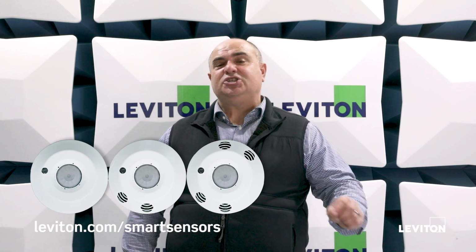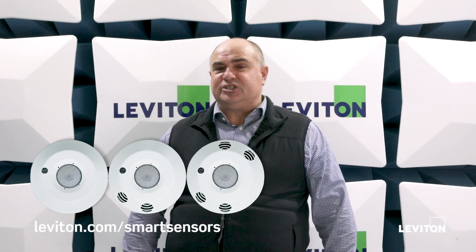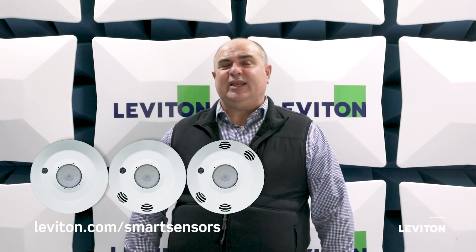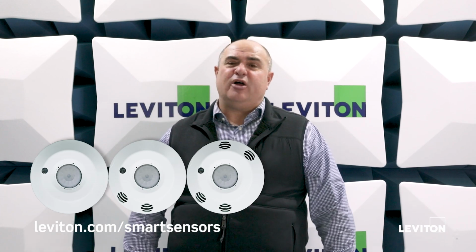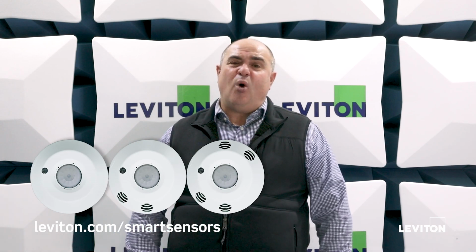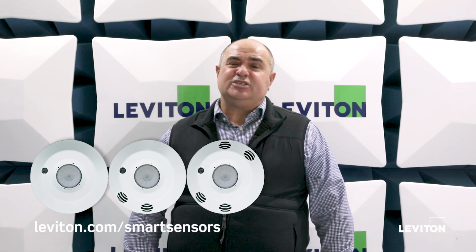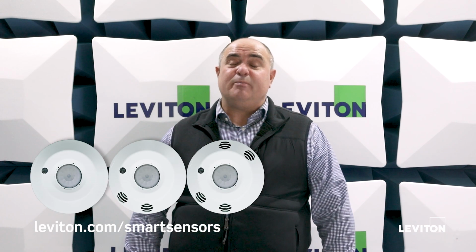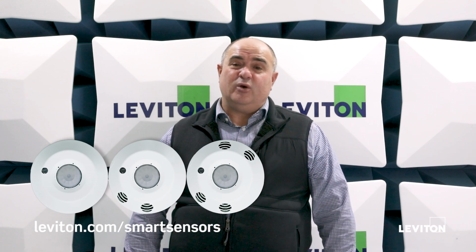It doesn't switch the power. The switching of the power is a UL1008 device, but in these applications where we need to bypass the control on the emergency lighting and allow them to turn on to the level required in the event of emergency or power outage, this inclusion of the UL924 solution within this device is a tremendous feature that was in fact added to it.